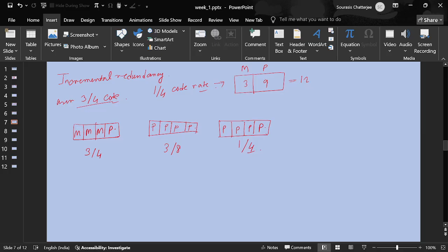You first have to design a particular code rate, then you do puncturing, then you create different redundancy versions, when to transmit, when not to transmit. And one more thing, does the order of retransmission really matter, if the redundancy versions carry the same information?